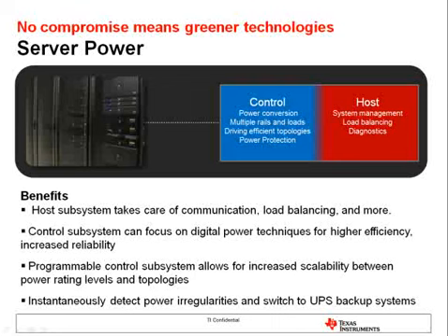There's also a need for system management, to balance the loads, to run diagnostics, to detect irregularities and quickly switch to UPS backup systems without skipping a beat. All of this information needs to be communicated back to a control center as well. The Cortex-M3 core can execute on every one of these aspects, ensuring that the C28X can focus on the power conversion.